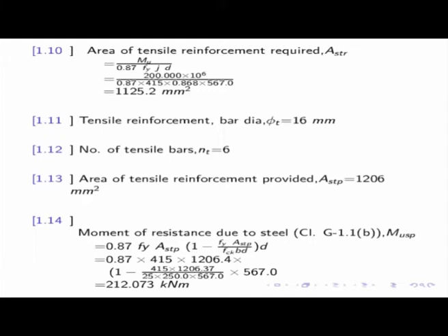That means we shall allow steel to fail, because then we shall get certain warning. But if concrete fails first, then we shall not get warning, because it is a brittle material, it will fail immediately without giving any warning. So this is the way we do the design. So this is the problem that we designed here.